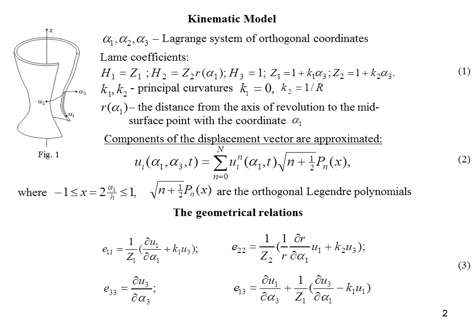It is believed that the two-layer shell of revolution is formed by cross-winding of the composite tape on a technological mounting made of mild steel. A kinematic model of deformation based on the non-classical theory of shells is used to describe geometric and physico-mechanical characteristics of the shell. For this, the components of the displacement vector are approximated by finite series of the orthonormal Lagrange polynomials. The construction of geometric dependencies is based on the relations of the simplest quadratic version of the nonlinear theory of elasticity.